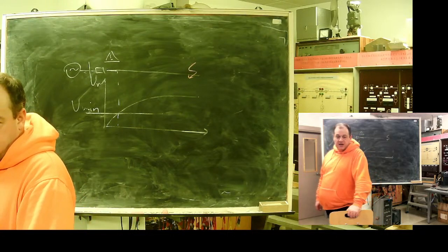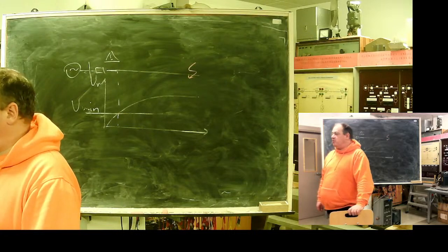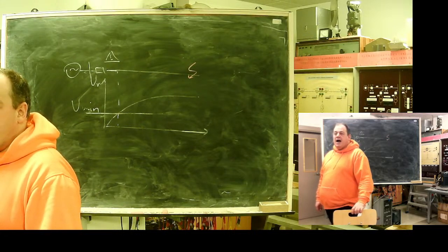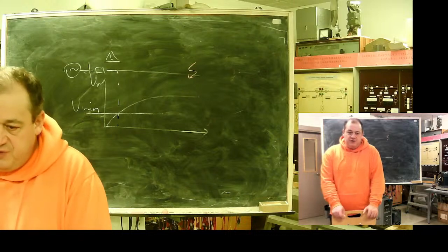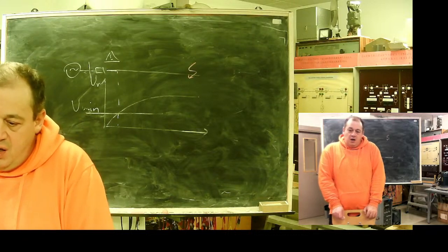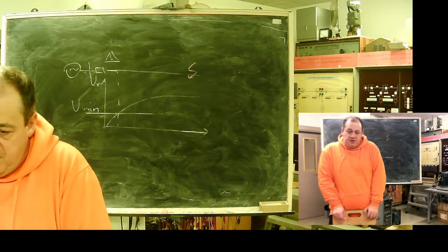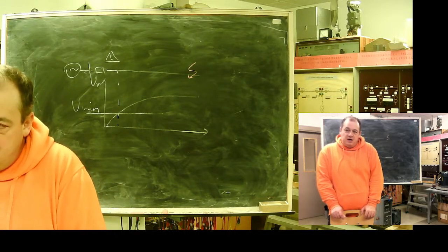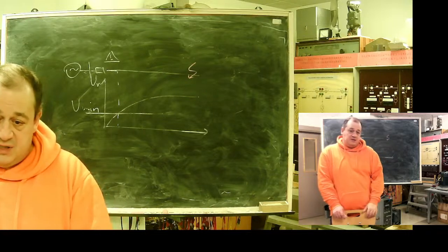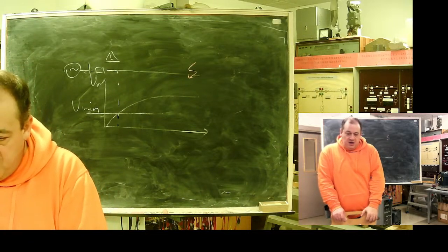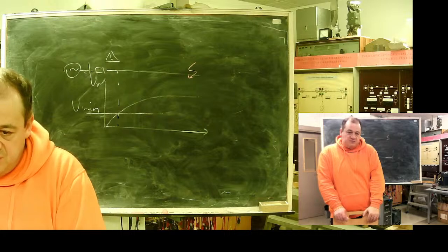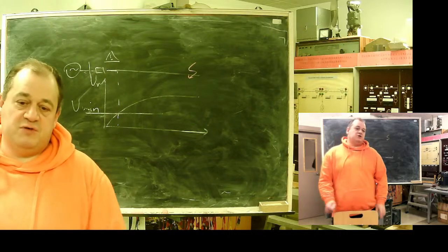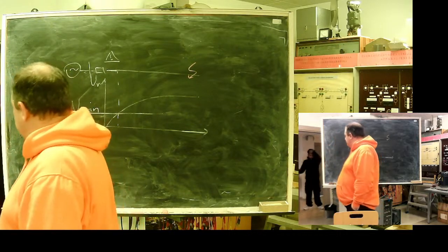to determine direction. But there is a problem with precision. A real problem: what happened? People worked on the line, protective safety earthing remained, and the line was switched on. Switch on fault.